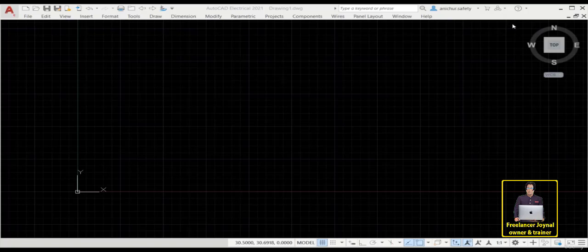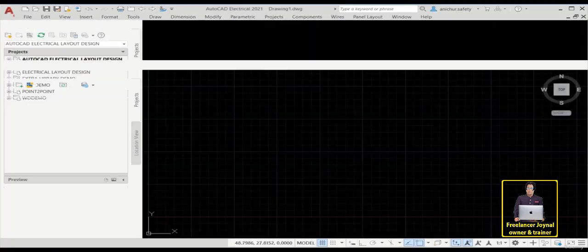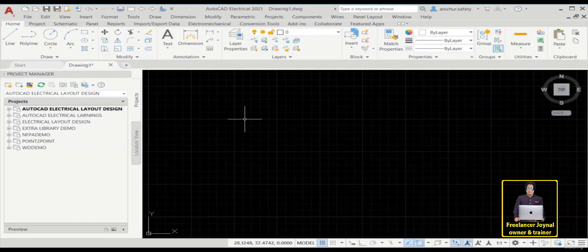Now we can see an AutoCAD workspace. This total area's name is workspace, but it's different from the default. Here there are no toolbars or ribbons. So how do we open all our toolbars? Just press Ctrl and 0 on the keyboard. Press Ctrl 0. Amazing. We can find our toolbar, ribbons, etc. Okay. Today our first topic is how to create and manage our workspace.